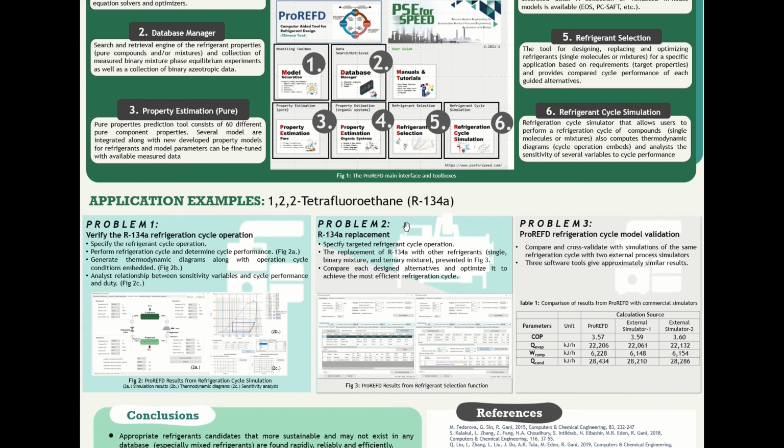The next problem is refrigerant selection. In the case of replacing the specific refrigerant R134A with other single or mixture refrigerants, the results of selected refrigerant alternatives are highlighted in Figure 3. Users can compare each alternative and optimize to achieve the most efficient refrigeration.